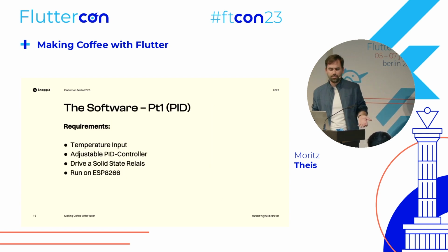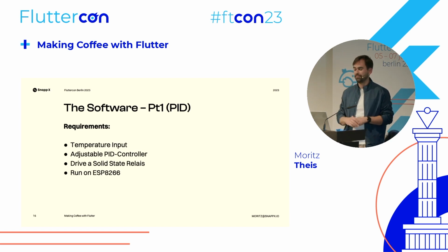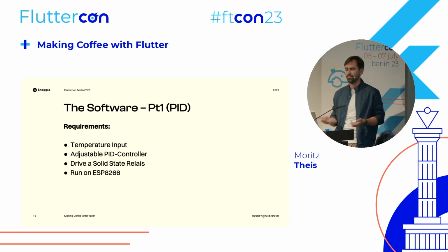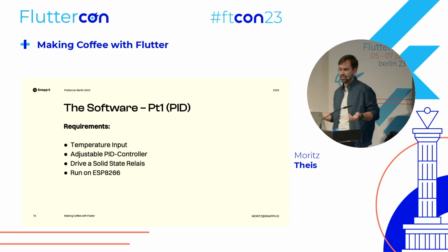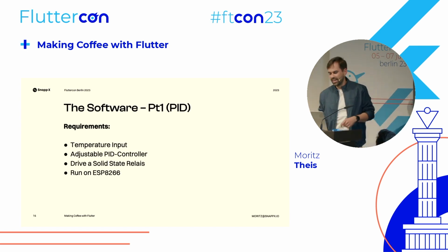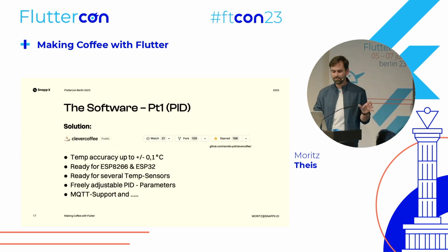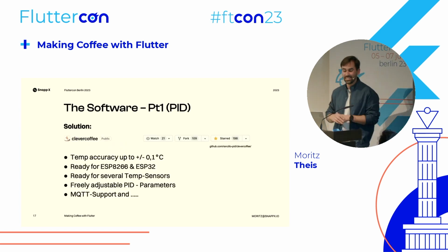So about the software, I needed to have embedded software that takes a temperature input, has an adjustable PID controller. I want to PID control the temperature, and drives the solid state relays. And it should run on the ESP8266. I thought, come on, I can't be the only guy doing this. And back then it was even harder. I think it took me a few weeks finding them, but actually there's communities around this,